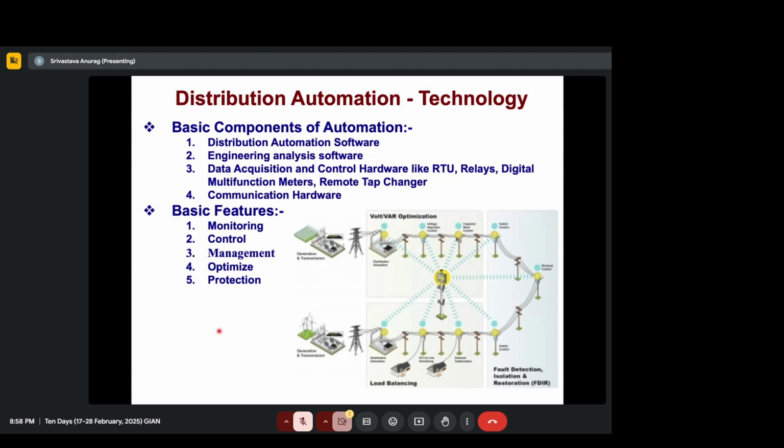So distribution automation technology, what does it mean? It means we are basically using digital technology, which is a communication network, sensing, to do things which we want to do with the distribution system at a faster rate, right? So we are putting in a lot of these intelligent devices, and we want to use the data for an automated way of detecting things, and an automated way of taking action through a set of software, which is either running at the pole top, in a box, or in the ground, or in the substation.